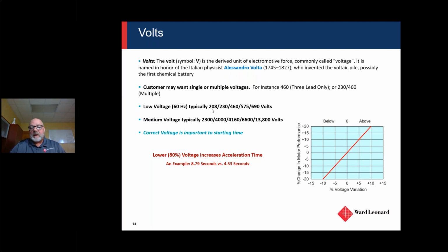That segment right there is the most common type of a 9-lead motor, and there's a connection diagram that tells you how to connect it. You've got to get that right. If you don't get that right, you will fail the motor, because it won't feed through the winding correctly, right? Different voltages require a different connection. Okay.